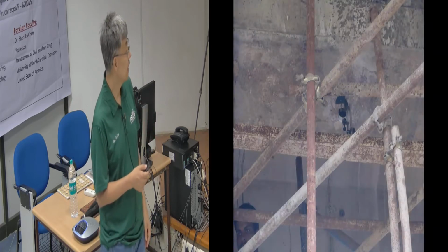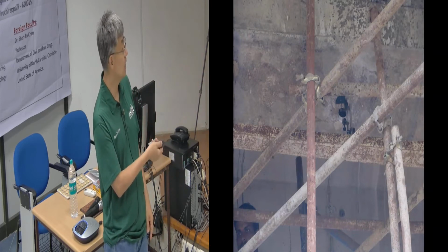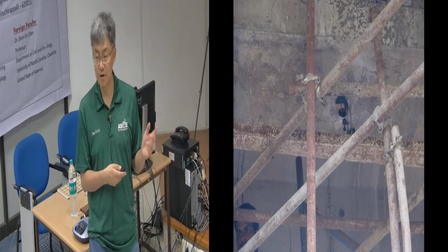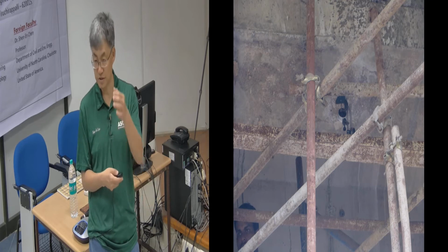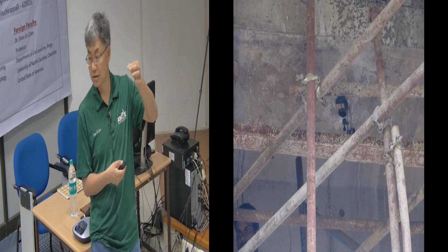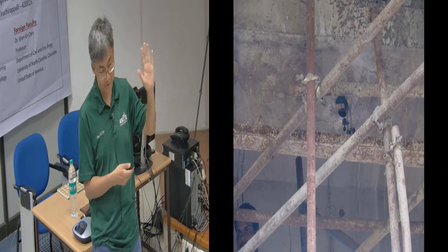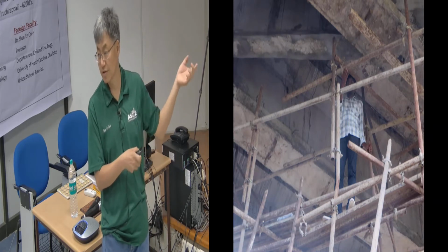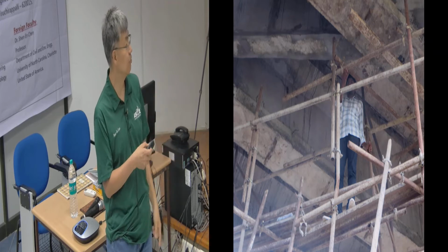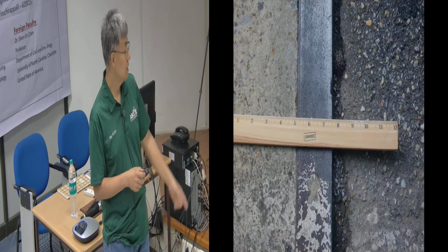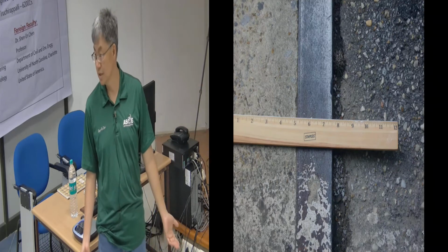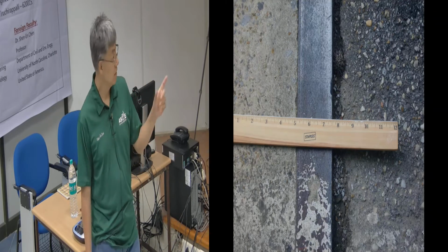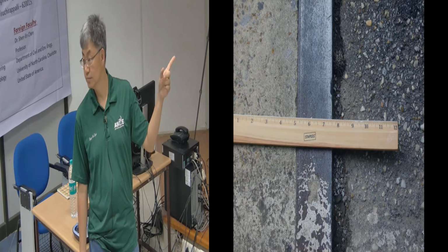Okay, and this shows the dial gauge that was placed on top. This very traditional method is still very useful, but very tricky to do. If you have experience using a dial gauge, if the dial gauge gets sticky, then it will not move, and your numbers become very erroneous, and it puts people at risk. They have to climb up the scaffold and literally do the measurements. Ruler measurements are good, but it is also very important for you to realize what the resolution of this ruler is.